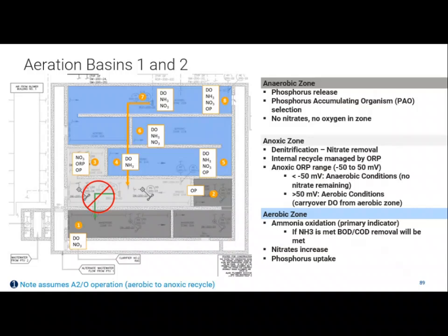And then they measure the OP. What do you want to see with the OP at the end of an anoxic zone? What do you think is going to happen to the orthophosphate, right? So you release it all here, right? What could be happening to orthophosphorus when you get through the anoxic zone? Yeah, because we talked about oxygen as being what PAOs use to grow with PHA, but they're okay with nitrate too, right? They're not beer snobs. They're okay with a little bit of Bud Light, and they'll actually do that growth with PHA under anoxic conditions, right? So you don't necessarily want to see your OP increase across the anoxic zones. You want to see it decrease.